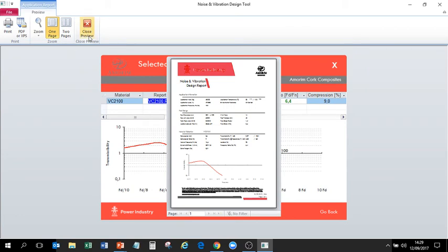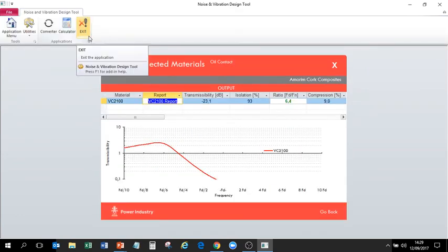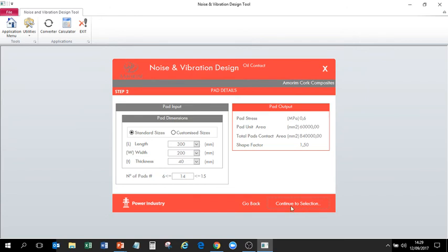So we have the information, but we can also change the solution if we don't like it. Okay, it's possible. We come back and we want to increase the stability of the solution. For instance, we want more pads. So as we are at the limit of the number of pads, we can decrease the size of the pads. For instance, 200 by 200 millimeters, using the same 40 millimeters, and you can see that the number of pads changed because we have changed the size of the pads.